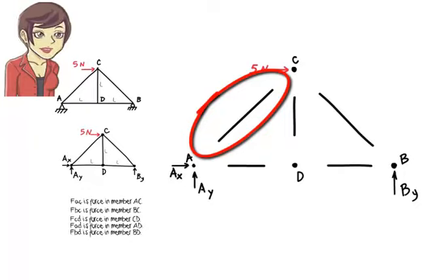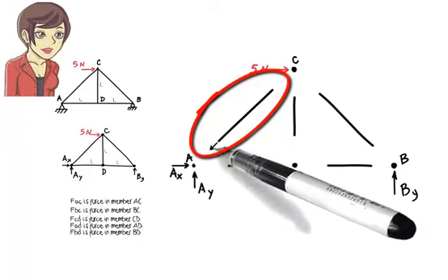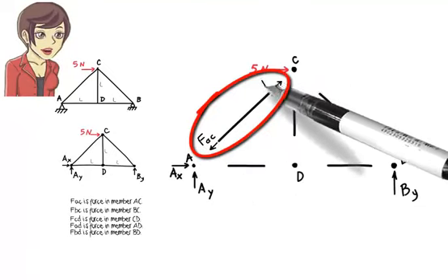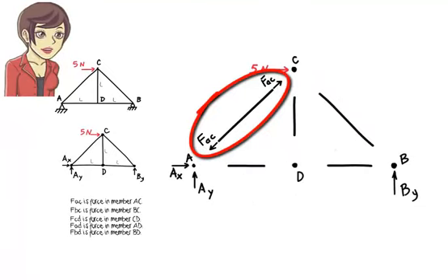Since I want to draw the free body diagram for the segment, I need to assume a direction for the force. I am going to assume the force is tensile. So the free body diagram for the segment looks like this. The only force present in the diagram is the unknown tensile axial force in the member labeled FAC.